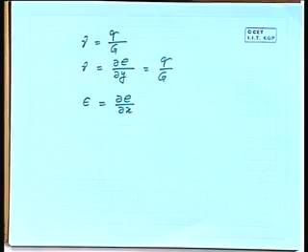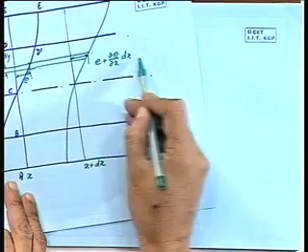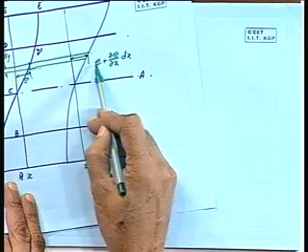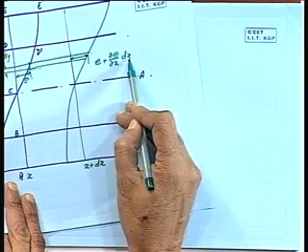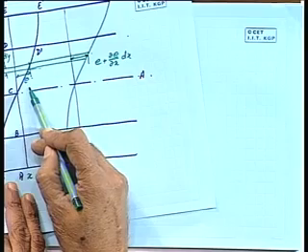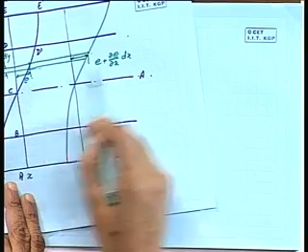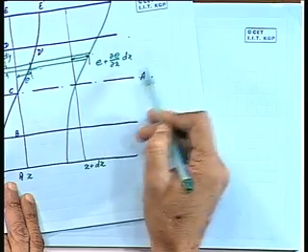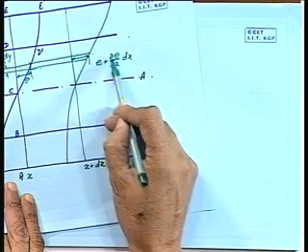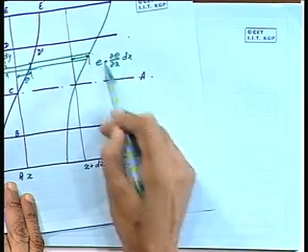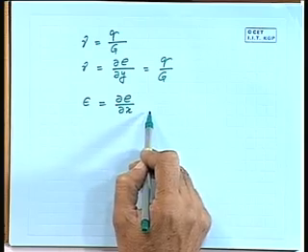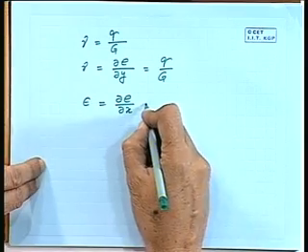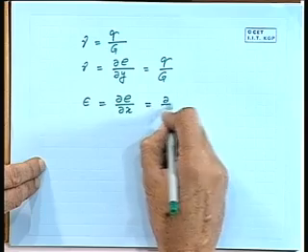See, this is the displacement here. So, net displacement is E plus del E by del x into dx minus E, and that is over a distance dx. So, divided by dx, what you will get is del E by del x, and that is the longitudinal strain here, right.